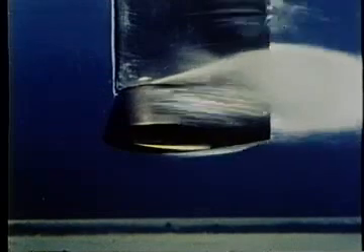At higher speed, and thus larger Reynolds number, the appearance of the cavitational flow changes. Transition from laminar to turbulent boundary layer has occurred. Laminar separation has been suppressed, and cavitation now begins near the minimum pressure point, close to the leading edge.